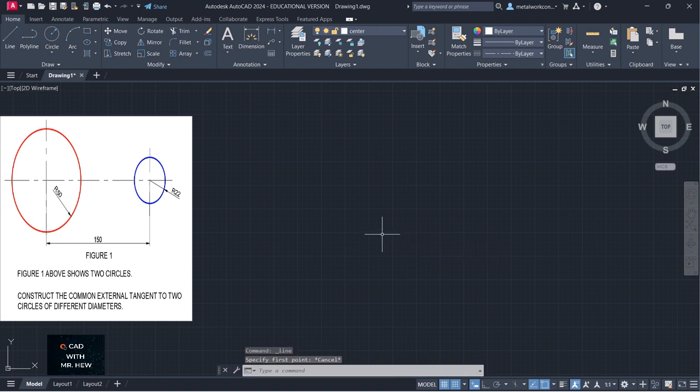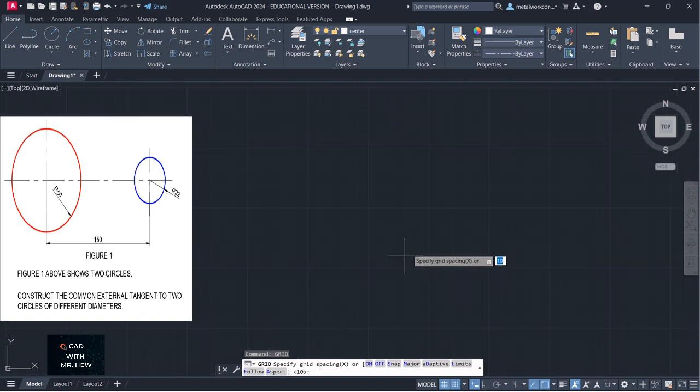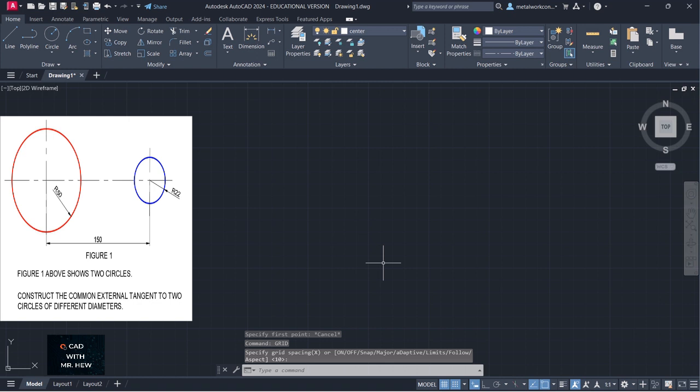All right, so the first thing I'm going to draw is a center line, okay? Oh, I also want to check my grid, GRID. The grid is like a graph paper. So each of these boxes, they measure 10 millimeters, all right? So each of these is a 10 millimeter spacing based on this setting. Then the next thing we're going to check is our snap.